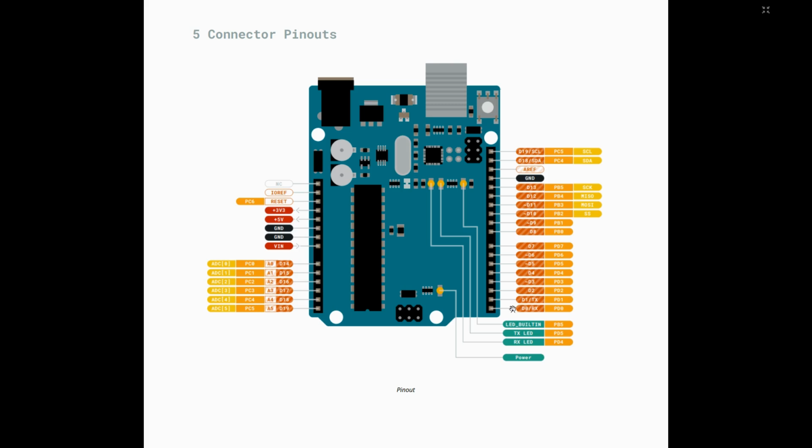So over here is the list of digital pins, in which you have D0, D1 and similarly D2, D3 going on till D19, and you can see that over here it says TX RX, which means these two pins are for TX and RX for communication with the other microcontrollers or with the other peripherals.